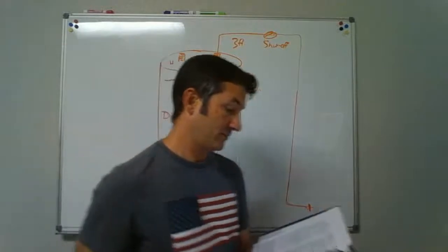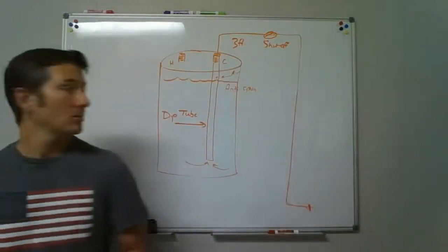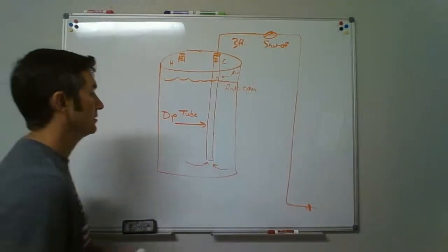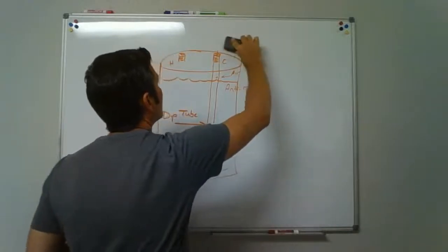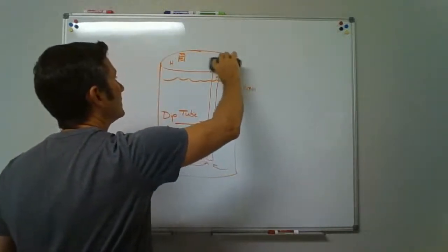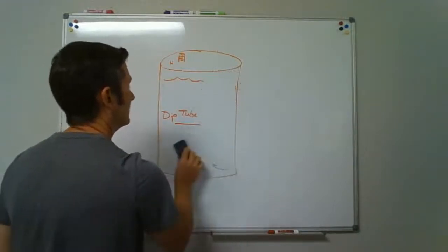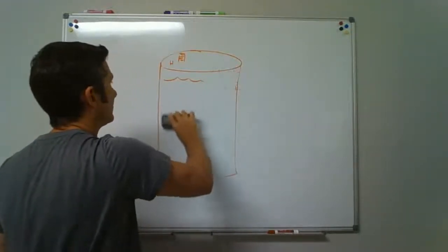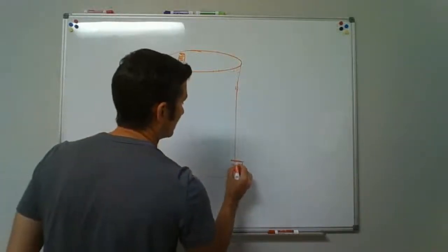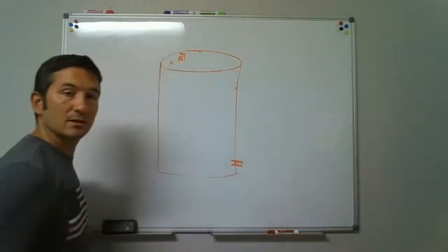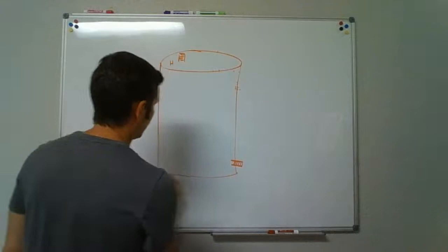Anti-siphon. Okay. Oh, it also did mention, while I'm still drawing pictures, this is a bottom-fed water heater. So now this one, it's a bottom feed heater, so it doesn't have a dip tube in it. Hot goes out the top. It's got a nipple down there on the bottom where we connect to. So you could take your water line and do it.